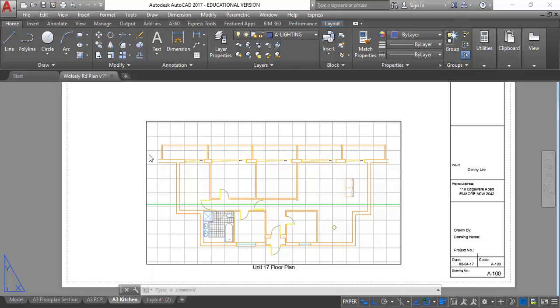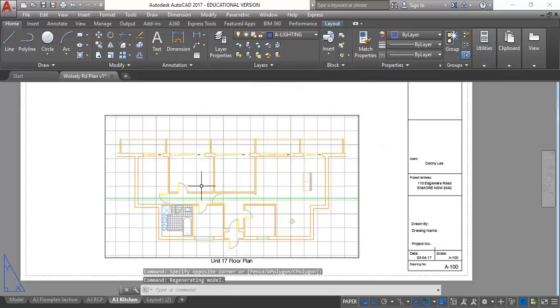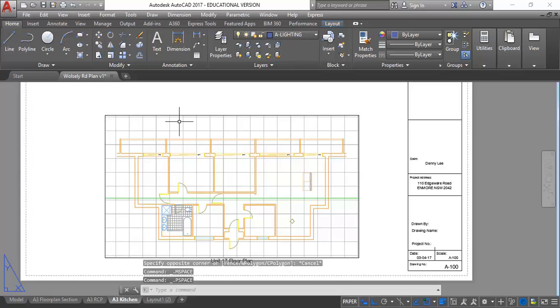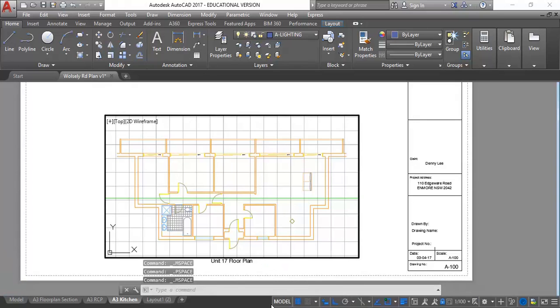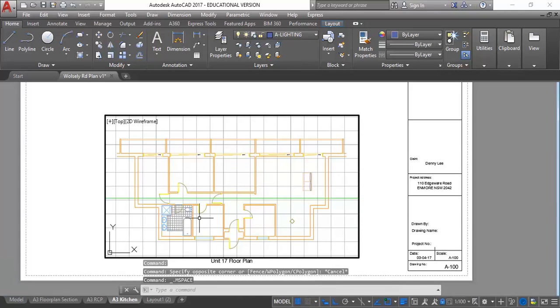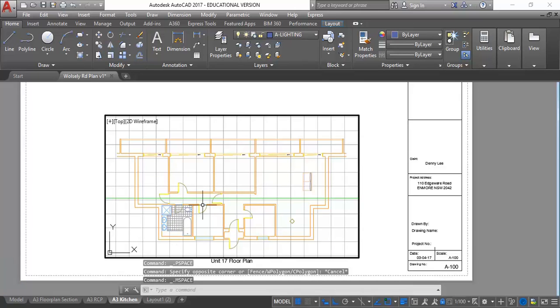That might be enough. So I've got the ground floor plan obviously showing the same way. So I'm going to double click to make that viewport active, and that's actually a shortcut you might find handy as well. You can obviously use the button I've been showing you down the bottom, but if you double click inside of the viewport, that does the same thing. If you want to go back onto the page, double click outside it, and it's the same as going back to paper.